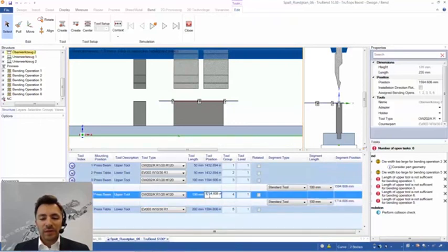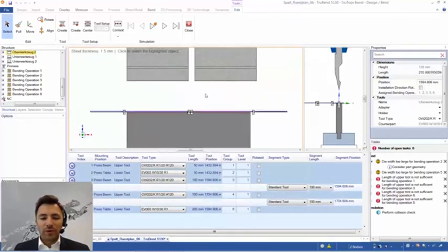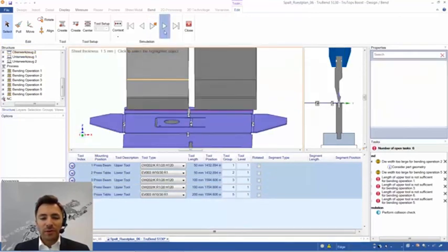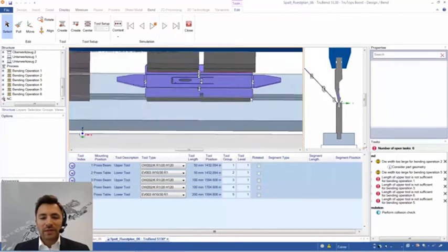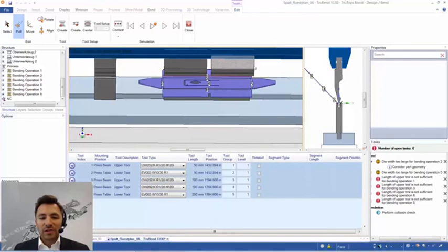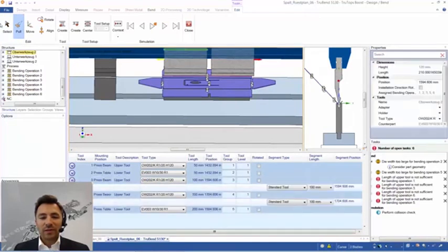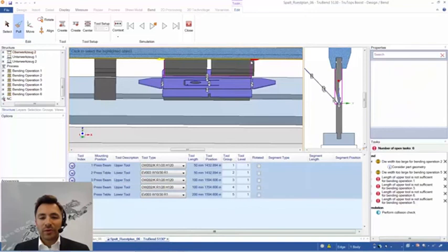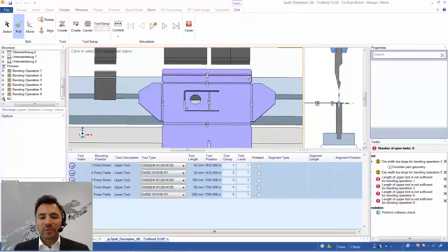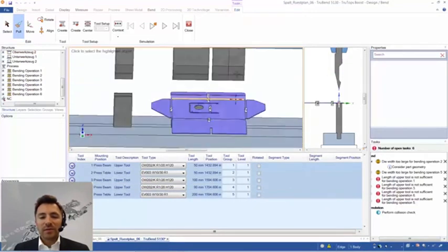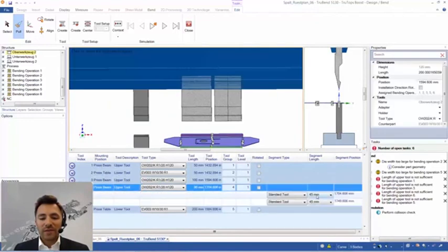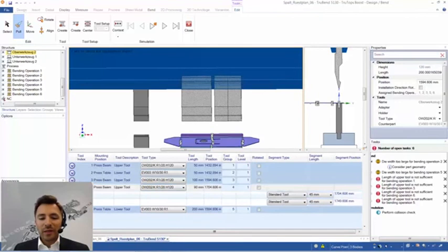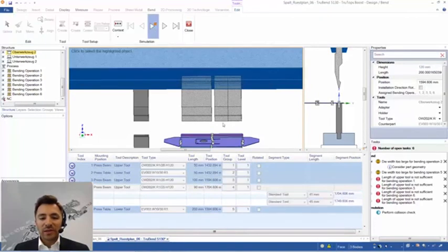So let's say it would be 1704. So I moved it a little forward, but we still see that it would collide with the other side. So I need to adjust the length as well, and therefore I activate the pull tool and pull on that side. I just pull it enough in, and you see that automatically there were 245 segments created, and that's basically it.